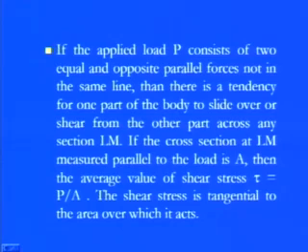Then there is a tendency for one part of the body to slide over another part, and that is why you see shearing, or shear across any section Lm. This is the great tendency of shear stresses: they always make the shear plane along the center line, or we can say the neutral axis. And the neutral axis is the axis where the centroid exists, or where all layers are well settled, in equilibrium within this object. So as we discussed, shear stresses are always set up in the object in parallel planes.